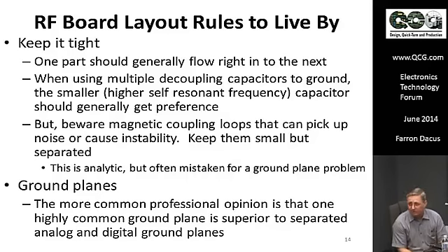I mean one layer, though it's not at all uncommon that you might have segments of ground plane on other layers for different purposes. For example, you can make a pretty good transmission line on a circuit board, called microstrip, by having a line of a certain width above a ground plane of a certain distance below it with a certain dielectric constant in the middle.